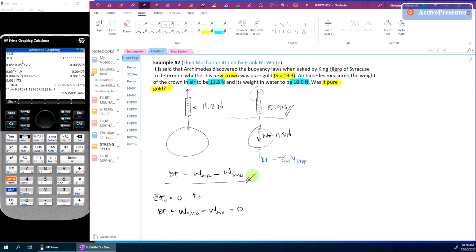So how do we solve this problem? There is a formula from the laboratory. We haven't had laboratory this school year so far, but if we get there, the specific gravity of the object is equal to the weight in air over the weight in air minus the weight submerged. You first weigh it suspended in air and get a reading, then submerge it in water or any liquid with known specific weight or specific gravity and take a new reading, which is the weight submerged. That's our formula, but we'll derive later why it is the formula.